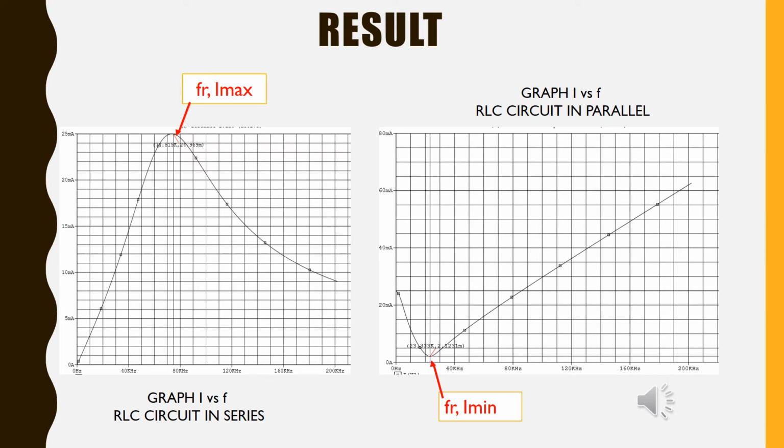They can get the value by using the cursor probe in the PSpice application. When they put their cursor at the peak, the value is displayed automatically. Students can write down the value, and when they do the hands-on experiment, they can compare the value and see if the value is the same as the simulation. This helps them to get the value earlier.